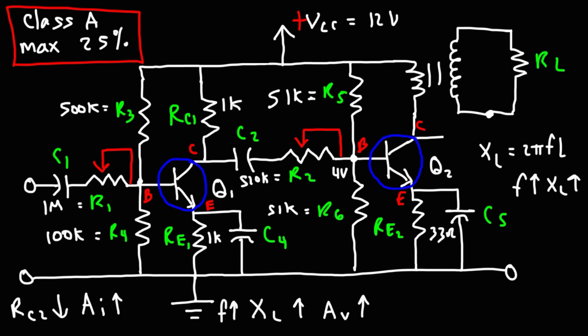But for the high pitched sounds with higher frequencies, those signals will have a higher voltage gain because the impedance is higher. And so the effective RC value will be higher for those frequencies. So that's the one downside of using this transformer, is that it'll favor high frequency signals, but it will reduce the amplitude of low frequency signals. So you may get a more high pitched sound.